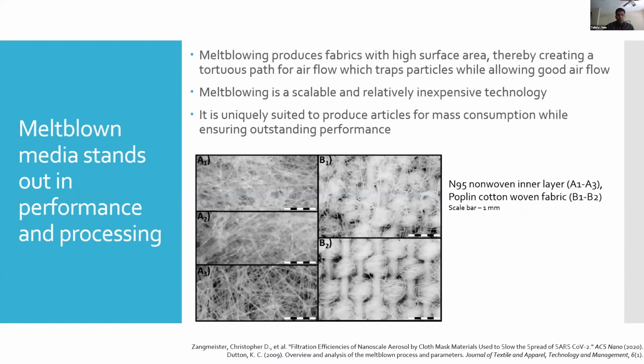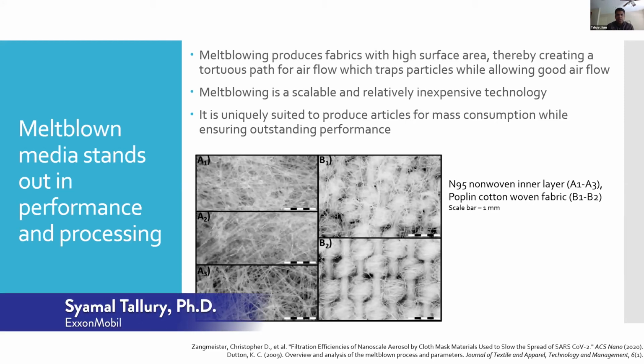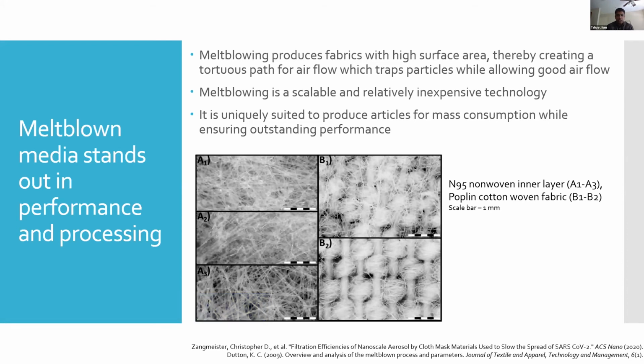Okay, then I'll move on to why meltblown is the material of choice. As we have pointed to you in the previous slide about the physics of this filtration, there needs to be successive layers of fabrics to really capture the large particles. But also there needs to be high surface area. There needs to be very small gaps or holes through which the particles can flow. And there should be some mechanism to also capture the superfine ones by these high surface area substrates.